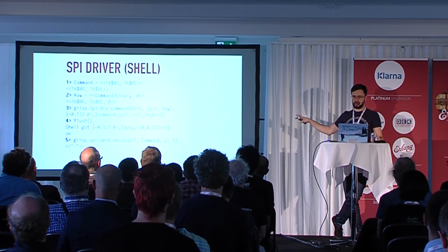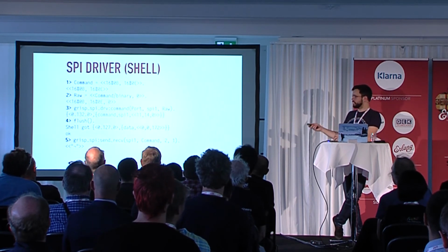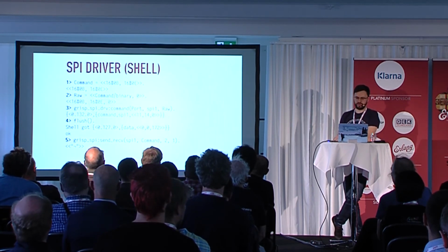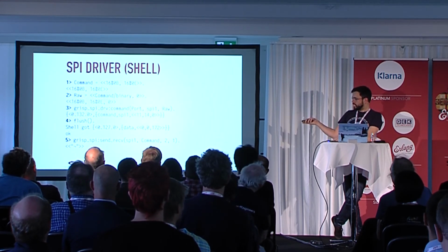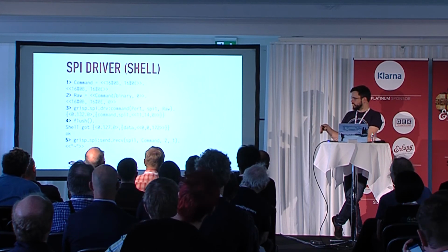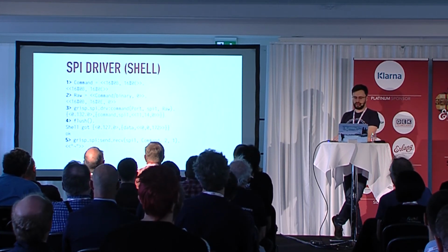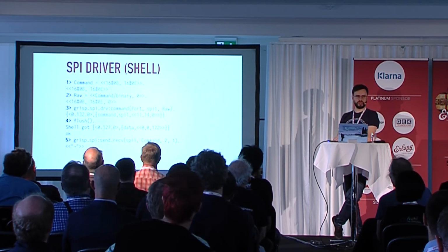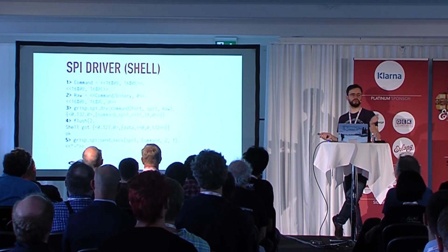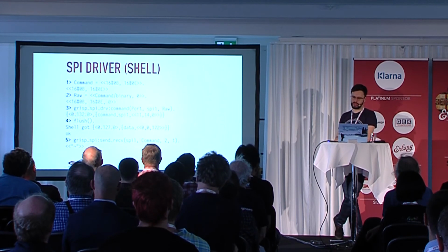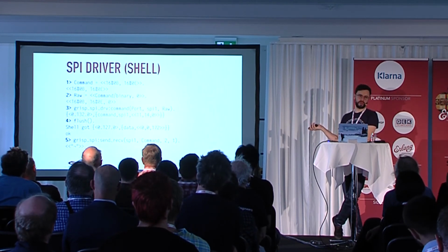So this is all very, very low level, but we also implement, of course, Erlang APIs to do this a bit more efficiently. This is an example of the same call, where instead we're saying, okay, I want to talk on SPI1, I want to send this command, please strip away the first 2 bytes and give me the 1 byte back. This will handle all the padding and cutting of stuff, so you don't have to think about this. This is what we use when we implement the PMod drivers, for example.